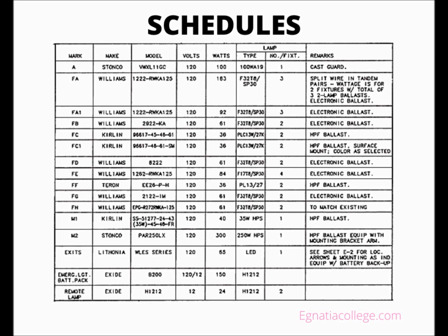Volts. It is becoming increasingly common for light fixtures to be powered by up to 277/480 volts. While the switches might use only 24 volts, low voltage lighting control, to protect the person using the switch. Watts. It is necessary to know the wattage of the lamps, bulbs, in each fixture, so that the space will have the amount of illumination intended by the electrical designer.